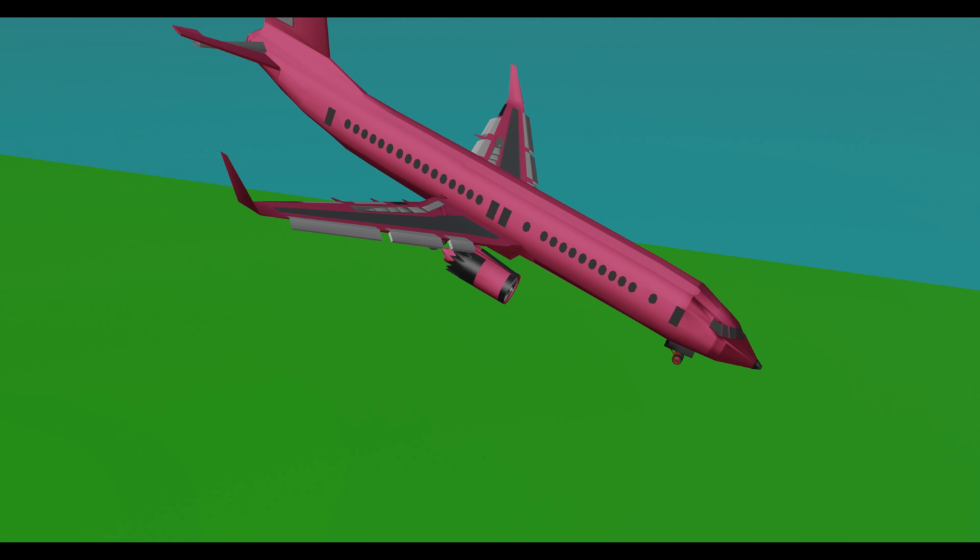When landing, the aircraft behaves in an almost similar way to takeoff, but in opposite mode. The flaps and slats are extended outwards. The elevator is turned and directed downwards. Therefore, the aircraft in turn pitches down, also deploying landing gear for touchdown.